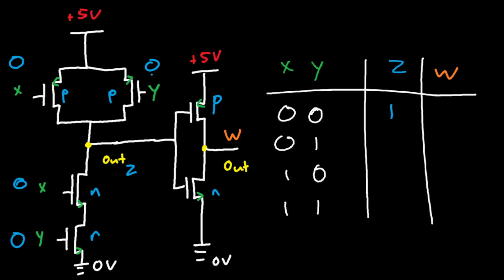Which means that you get a logic of 1 for 0, 0. Alright, let's take a look at other logics. Let's look at 1, 0 next, because I already erased that, might as well just skip a little part. But 1, 0, this acts as a closed switch, and this acts as an open switch now. That's the only difference.